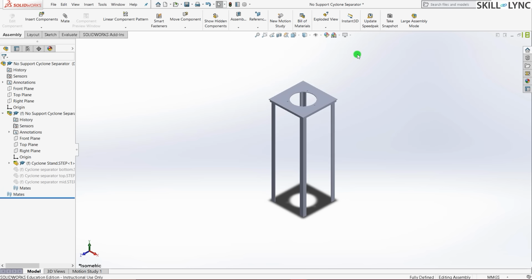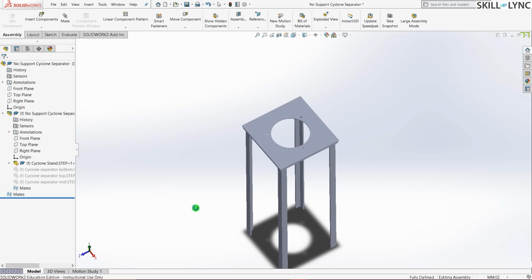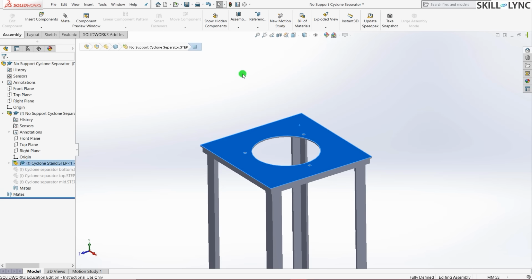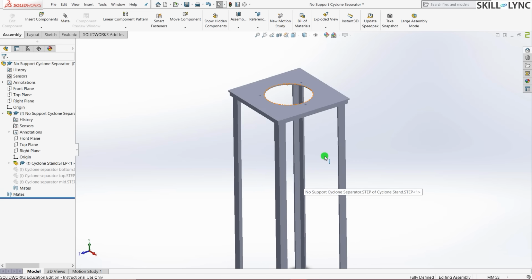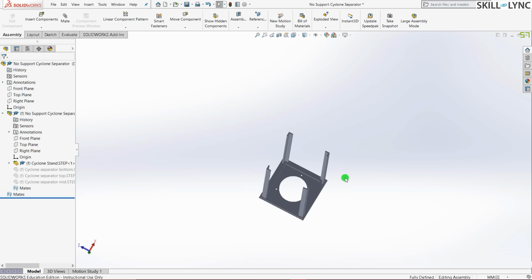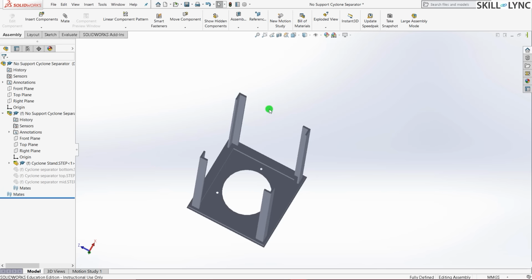To obtain our buckling factor of safety, initially you will be applying a certain value of force here directed downwards. That will cause buckling on these 4 legs of the model, and you will be given a certain buckling factor of safety, and also you will be receiving a target. Similar to how 20 was our target, the target for this will be available for you in the question, and your goal would be to create a stiffener in such a way that you will be increasing the buckling factor of safety of this model.